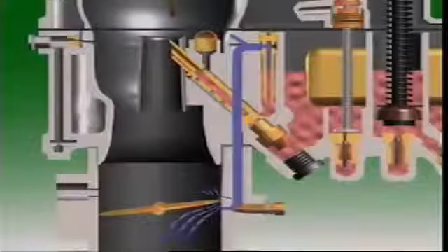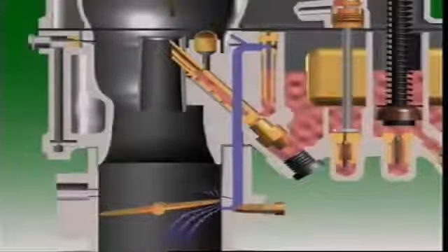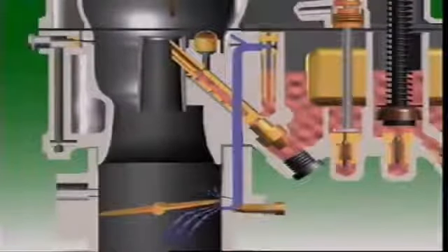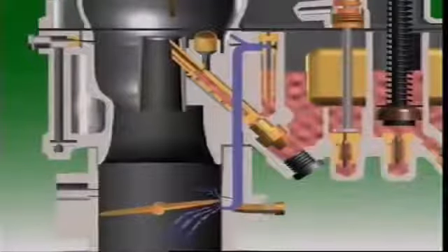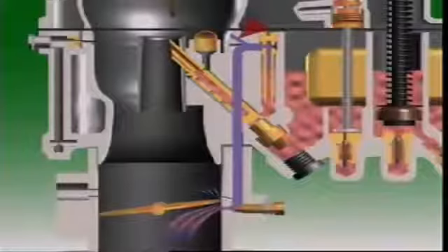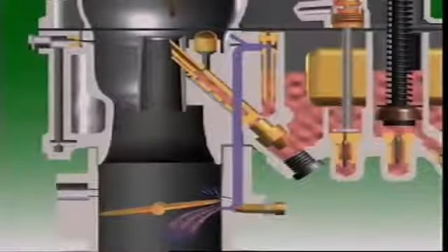The action of the piston creates a low pressure area below the throttle, and this is concentrated at the edge of the throttle valve as the air passes the idle port. Fuel flows from the float bowl through the idle passages and into the carburetor below the throttle valve at the idle port. The air bleed lets air enter the fuel on its way from the float bowl. This helps aerate the fuel before it reaches the idle port. Engine idle speed is set by two different adjustments.